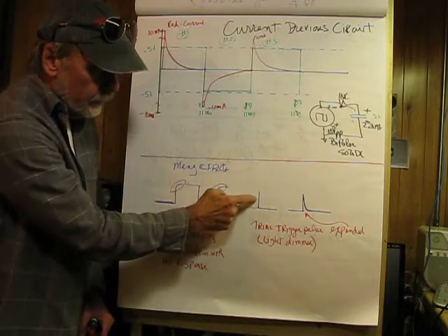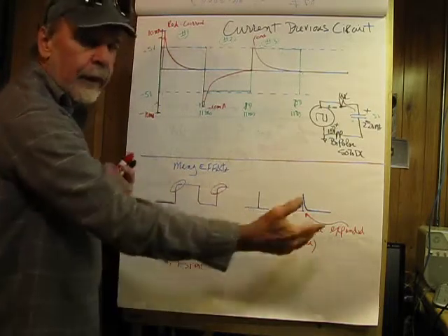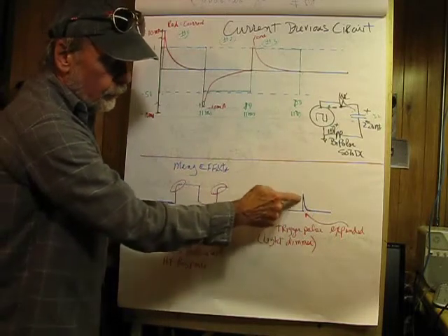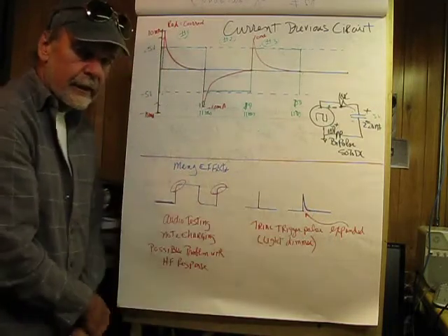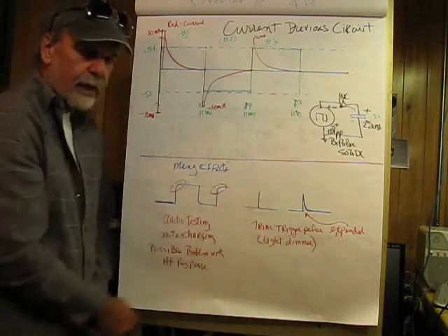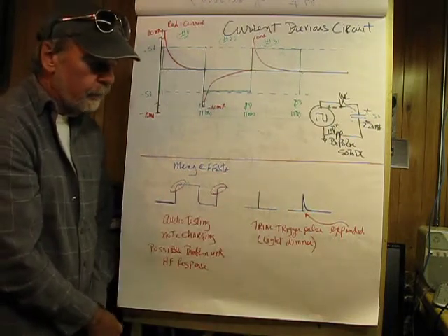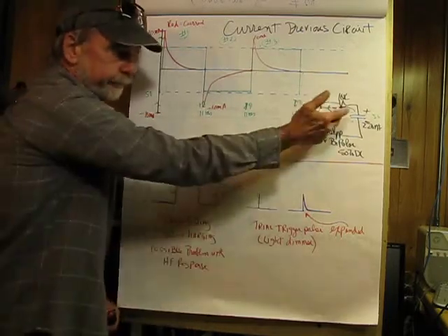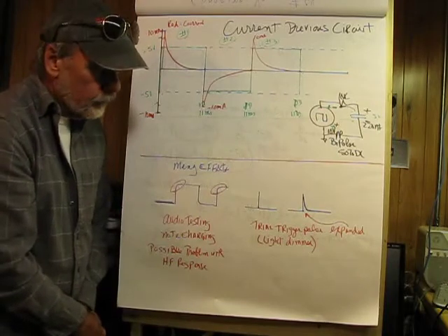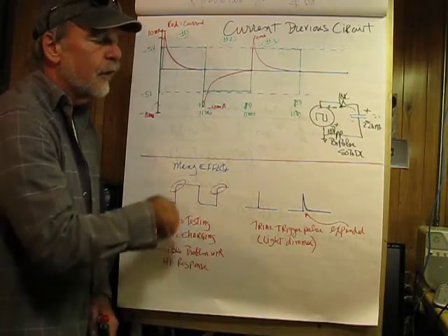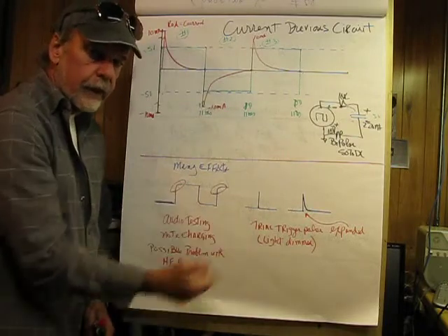But if we take this spike and spread it out on a scope, with the time base, what we'd see is that it's actually a decaying exponential. Now, if I showed you the circuit that's driving the triac, what you would see is an R and a C that's coupled into a special device called a diac, which is going to dump C into the triac's gate.